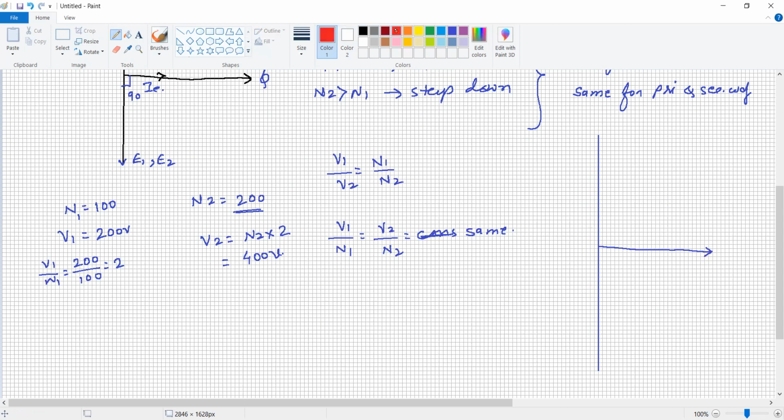So here this is the flux phi. The voltage applied is V1. To produce the flux, some exciting current IE is required to flow. We have drawn this exciting current exactly 90 degrees with respect to the supply voltage, because we have considered that there is no eddy current and hysteresis loss, but it will make some angle with respect to phi. Okay, we will see one by one.